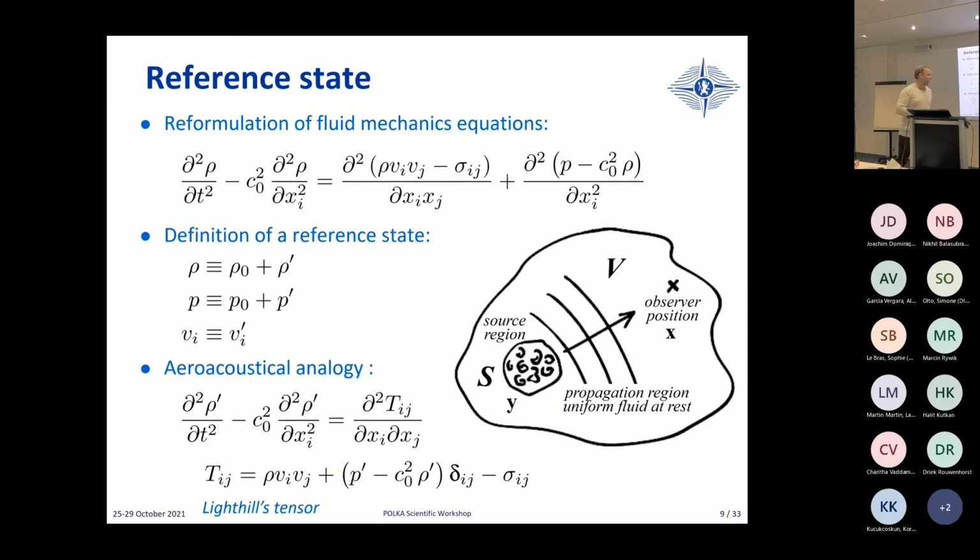So just to finish this, I'm not going to go through the whole reasoning, but at large Reynolds numbers, we know typically that the Reynolds stresses are going to be dominant over the viscous stresses. Okay, that's what characterizes large Reynolds number flows. And for reasonably isentropic flow, like an isothermal jet, anything without violent mixing, chemical reaction, or anything that would cause some significant entropy variations, this is going to be negligible as well. And then the remaining term will be the Reynolds stresses.